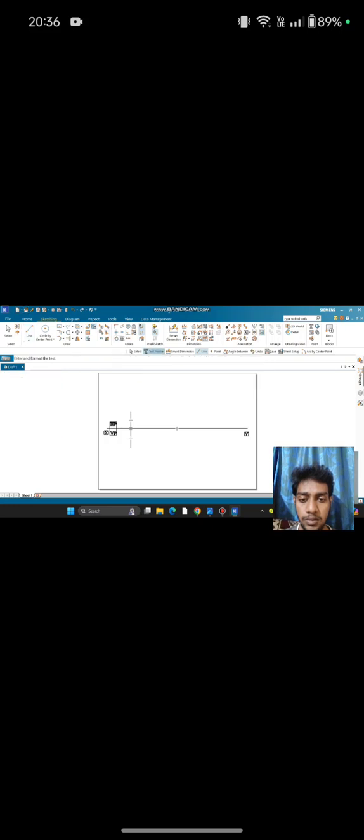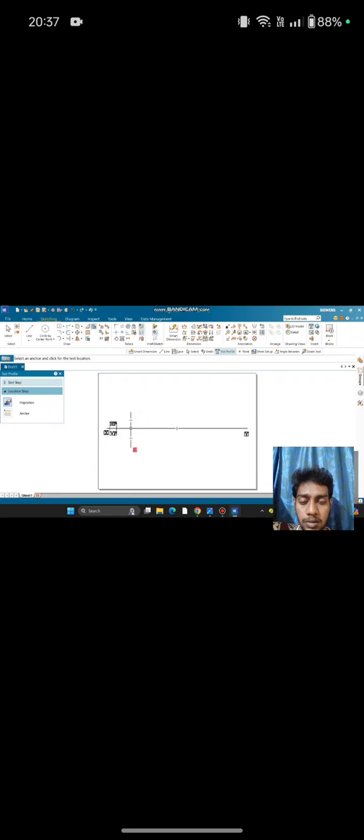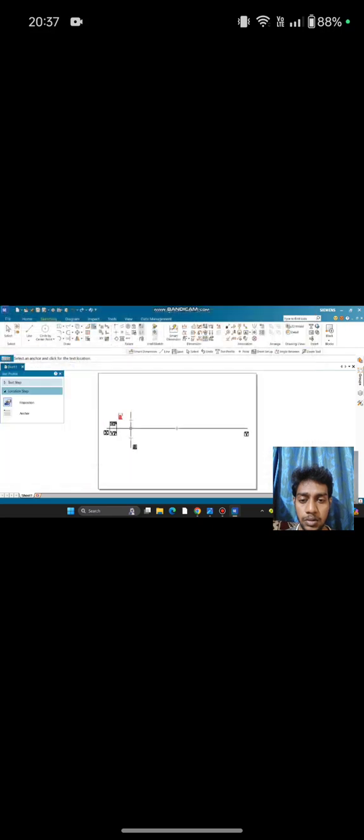Now let's mark this using the Text Profile. Keep this as A, enter, OK. This will be A. Again go to Text Profile, mark this as A dash, click on OK, mark this. Then go to the Smart Dimension button, click on the line and see its dimension.